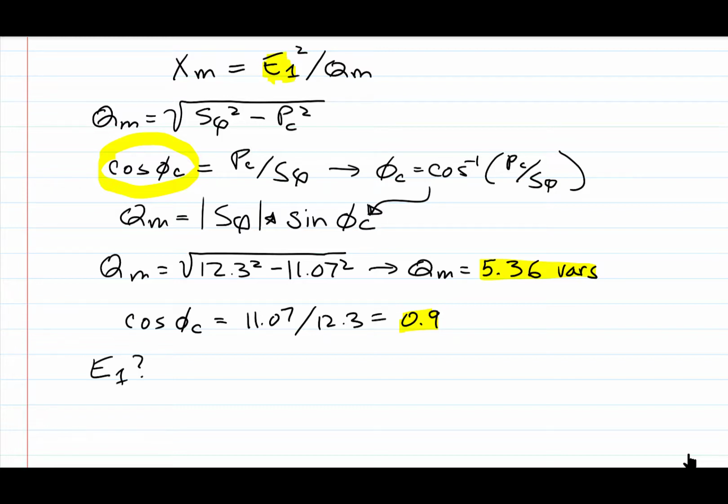Well, in this handout example that I gave, we could have used V sub 1 and ignored the leakage inductance. Here we have a direct calculation, though, of everything, because we've calculated the P and the Q from the actual physics and physical characteristics of the core, and we've directly measured the secondary winding, V2. That's equal to E2.